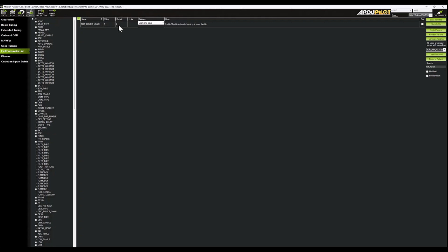But once again, my recommendation, don't touch it at all and just set that parameter that we just discussed to 0.5. And later we'll initialize all other parameters. Hovering is a really tricky thing, especially if you are attaching different payloads to FPV. In general, it's better to learn it with the payload that you are planning to use.